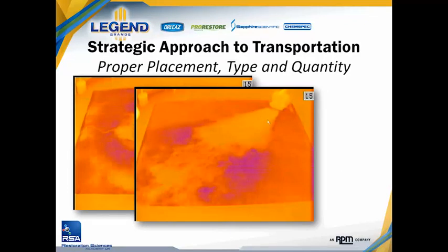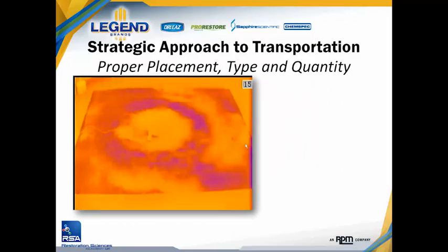Now, this image is important for helping us understand both the importance and the impact of an air mover. We learned several things from this. One, our drying rate is always going to be fastest where the air movement is moving the fastest, and that's where we have the greatest speed, closest to the air mover. It's also going to only be impactful when the air is in direct contact with the surface. As we saw from the first image, where we had direct impact from airflow, we had great ability to dry, but as the air literally began to bounce back up off the floor, we lost the influence of some of that airflow. Those are two very, very critical, very important lessons for us to know and understand.